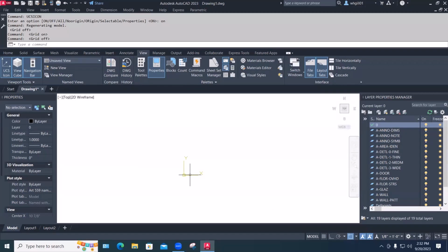And the reason I'm going to make this point be 0, 0 in this block is when we end up placing this back in our drawing, the cursor will be right there and we'll move it around by its center point. If we let the center point be down here, I'd be moving the cursor here, but the block would be off it, which is just very disconcerting. You like to have this in some intimate way connected with the object itself.